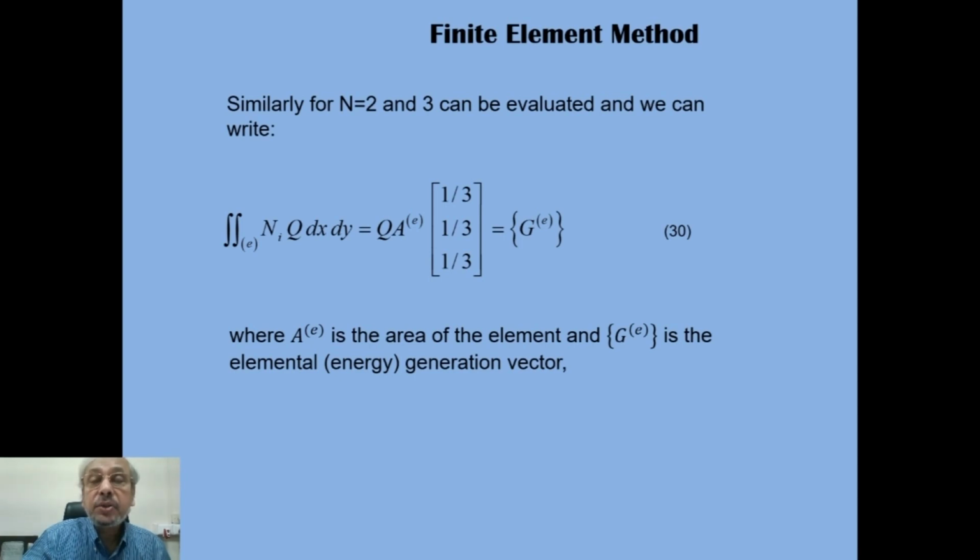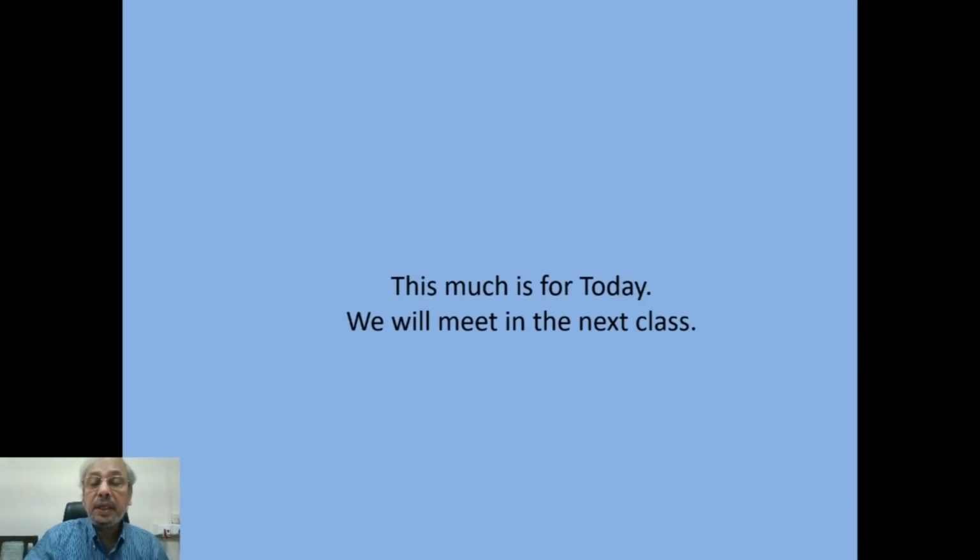Then also it has to represent the complete domain, so we have to establish the elemental connectivity, global and local node number connectivity, etc. So the evaluation of the remaining terms of the integral and setting up the final matrix form that is to be evaluated to find out the temperatures in the entire domain, we will take up in the next class.